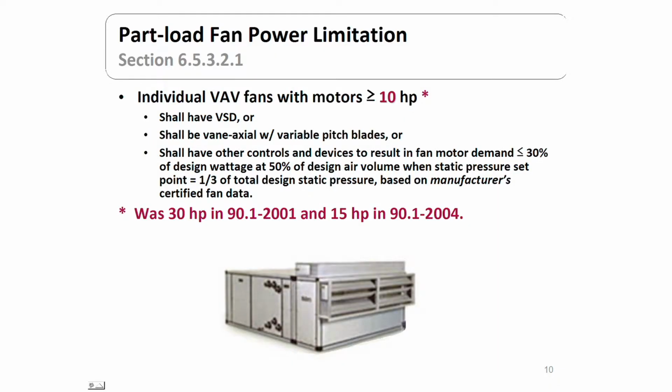Anyway, they have to have a variable speed drive, a VSD, or they have to be vane axial with a variable pitch blade, or they'd have to have other controls that result in a fan motor demand being less than 30% of the design wattage when there's 50% of the design air volume. That's when the static pressure set point is at 1/3 of the total design static pressure.